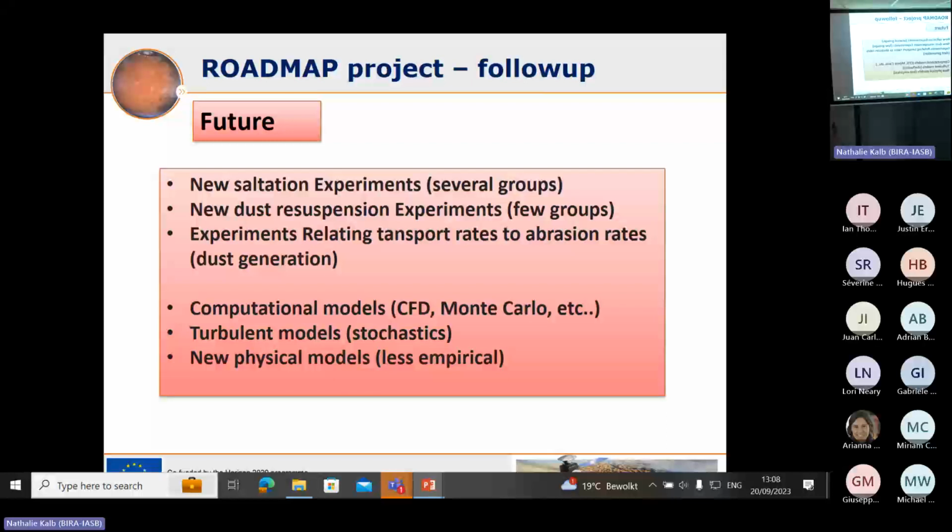A technology we've been using a lot now is pitot tubes, which are very, very simple. They just require measuring pressure differentials. You could have loads of those. They're very lightweight, very low power, easy to build. Or you could send something more advanced like a sonic anemometer. These can work in different dimensions, and that can also tell you about the boundary layer. I know there is an American group coming here actually soon to my lab. They're developing a sonic anemometer for Mars.